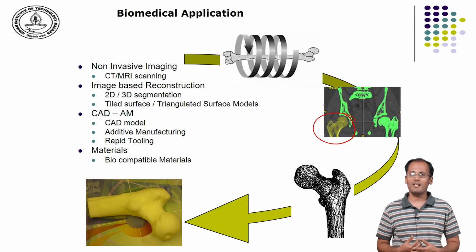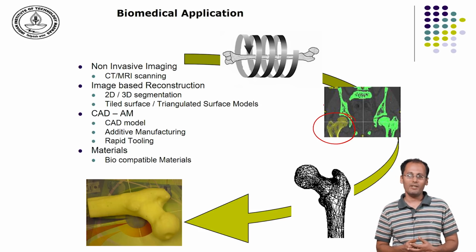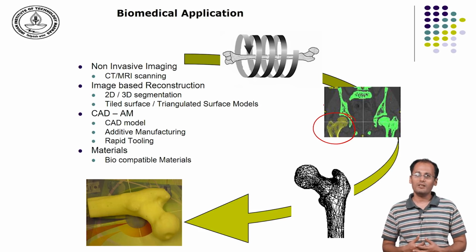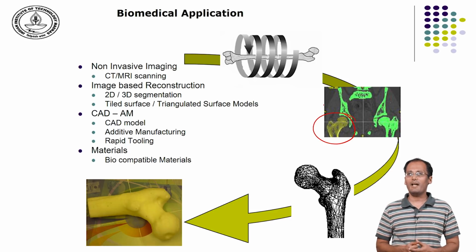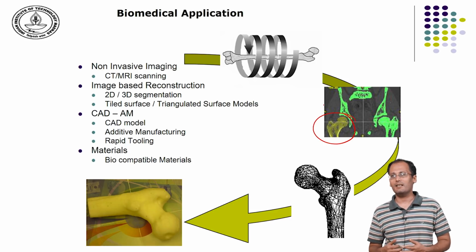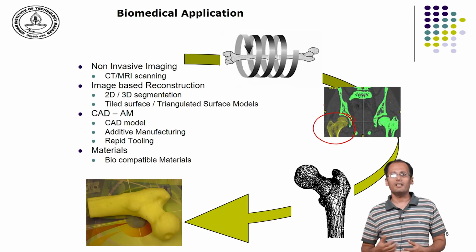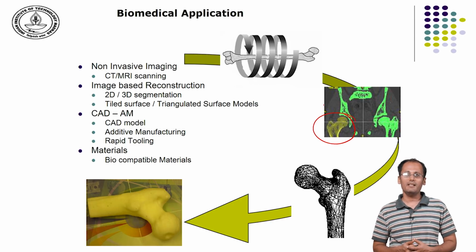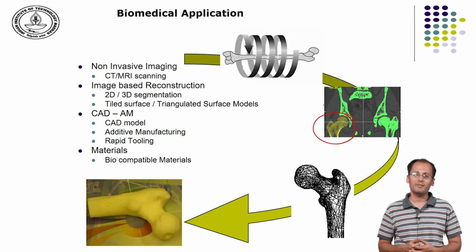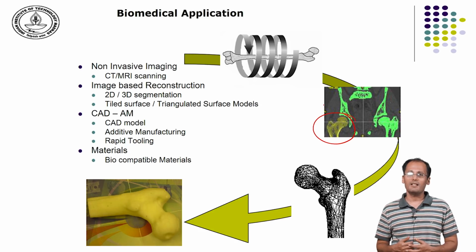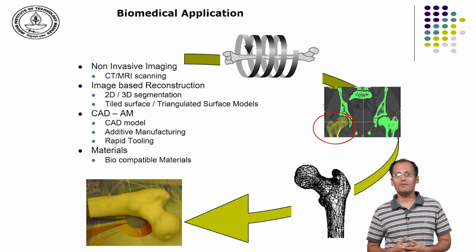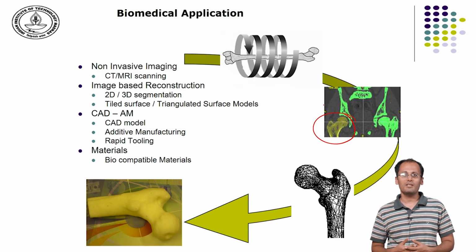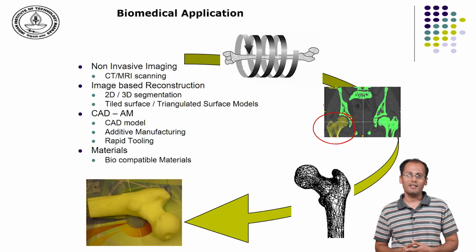Complex geometries are already being enabled using topology optimization frameworks. One has to also now have frameworks which can use heterogeneous material distribution or functionally graded materials, and try to create object or part design frameworks which can use these enabling factors.